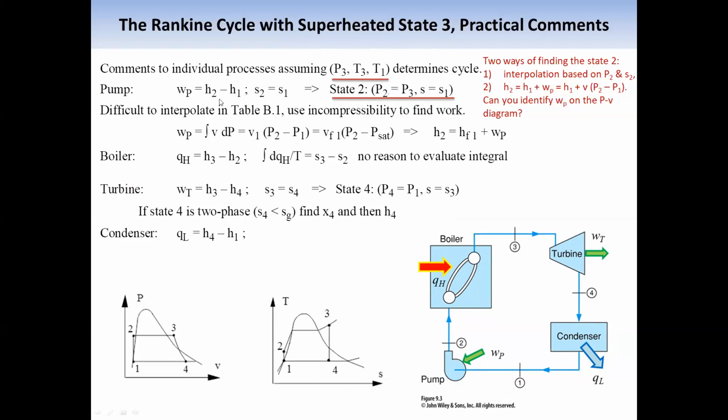For the pump, it's the same: energy equation, entropy equation, but for state 2, pressure the same, entropy the same.